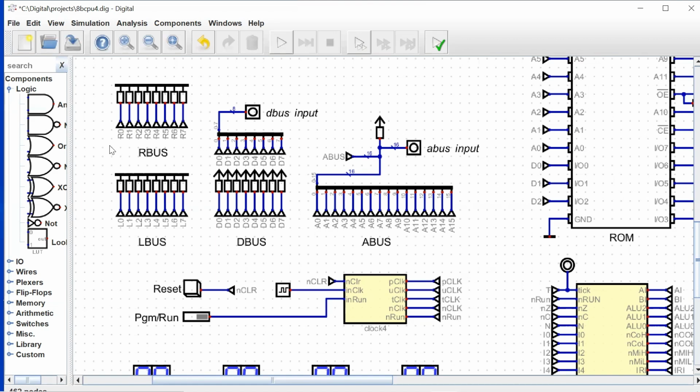You'll remember that when we do that, we use a logical OR operation, and whatever data is coming from the left bus, when we OR that, we want to make sure that the right bus floats to 0 when it's not being driven, so that we get a good data transfer through the ALU.